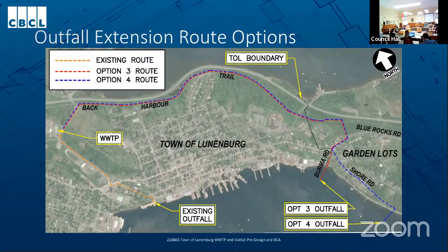The pipe size for the force main is in both cases a 14-inch pipe, and for the gravity section will be a 15-inch pipe. This is to get a balance between the flow going fast enough that solids don't settle out into the line, and also not so fast that there's excessive energy losses due to friction.